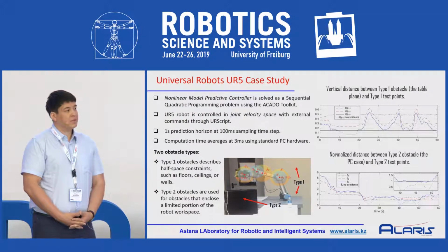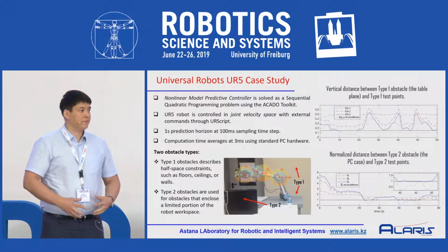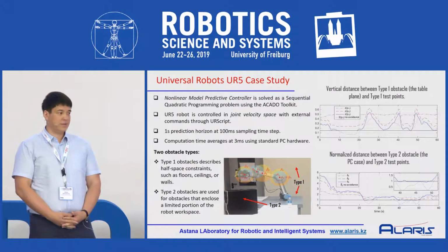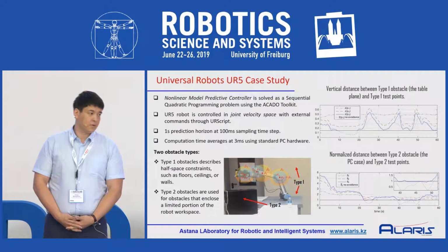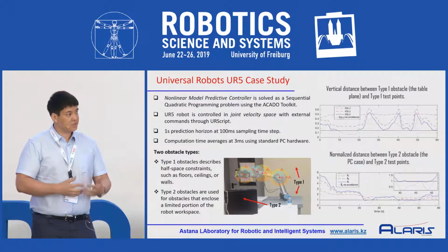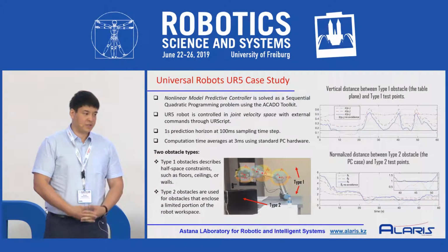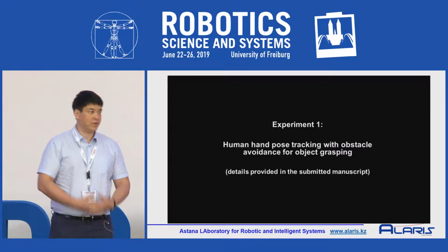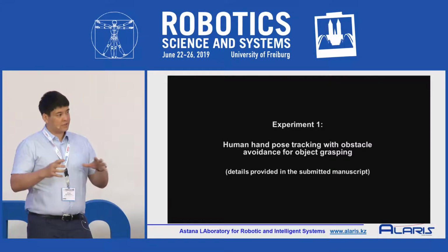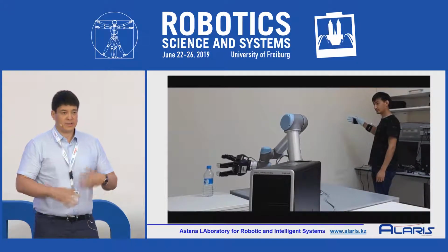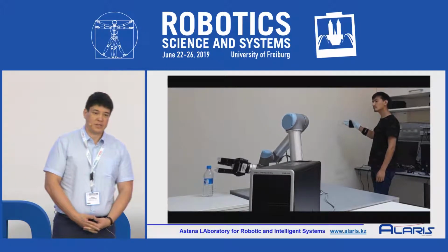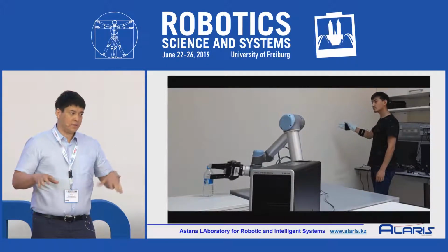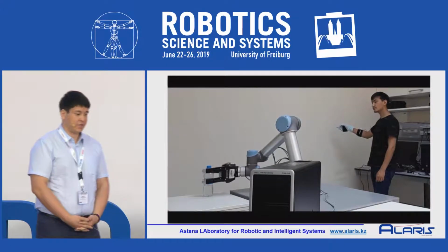At the same time, we also model the robot frame itself, covered with convex shapes like spheres, so that the optimization problem generates the trajectory while comparing the convex shapes representing the obstacle and the robot frame, so that the trajectory avoids collision between these convex shapes.